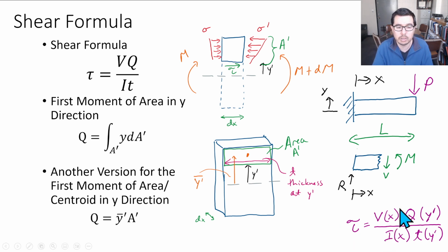So it's important to have a perspective, because there are essentially four quantities that, with the exception of maybe the thickness, require other calculations that then plug into the shear formula to calculate the transverse shear stress.